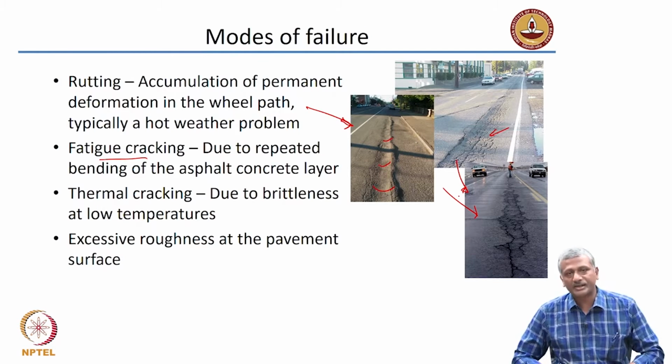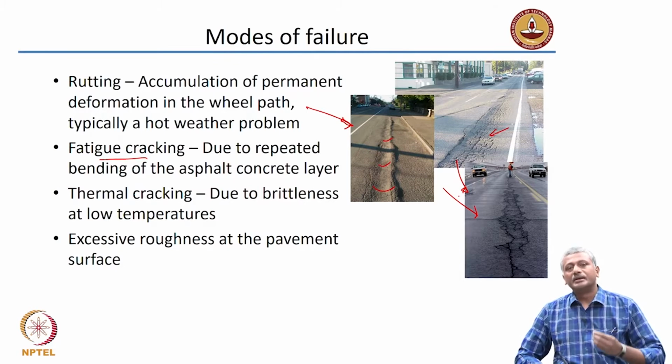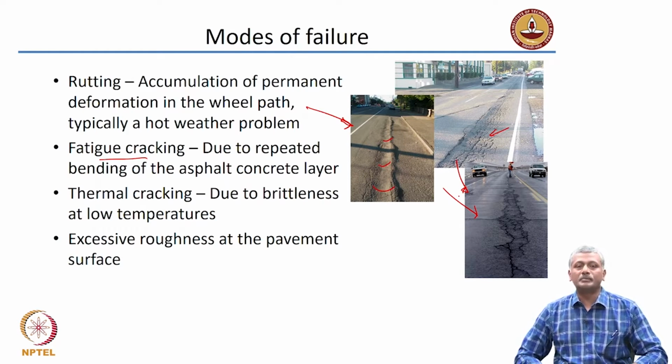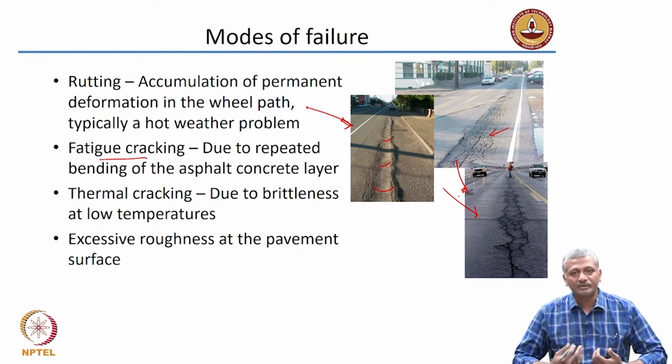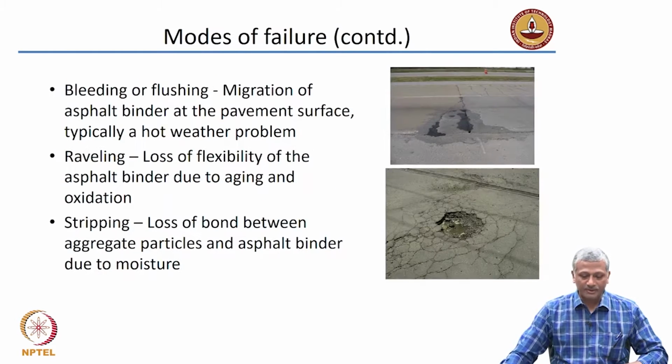We talked about this in the case of polymers also previously. There we had this important temperature called the glass transition temperature. That is the temperature at which the elastic solid nature of the polymer gives way to a viscoelastic solid nature of the polymer, and because of that the polymer starts deforming, and some of this deformation is permanent, it is accumulated, and because of which you have a failure because of excessive strains in the material. Now, let us look at other types of failures.